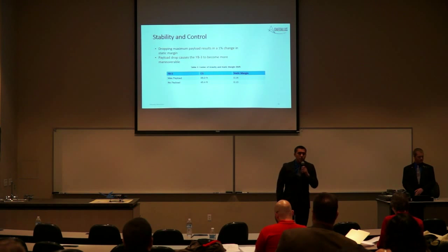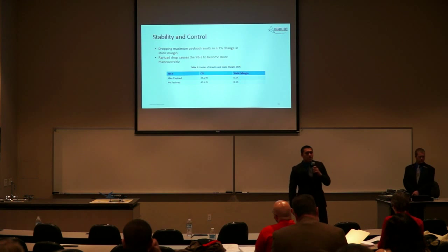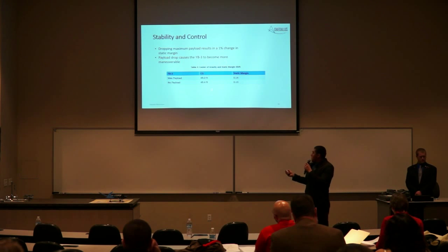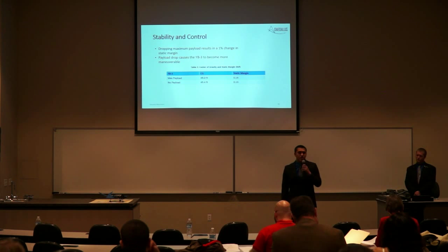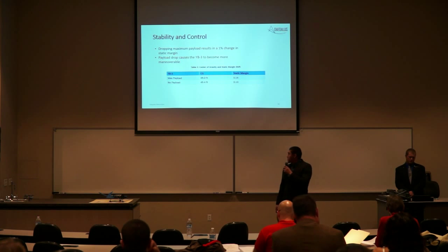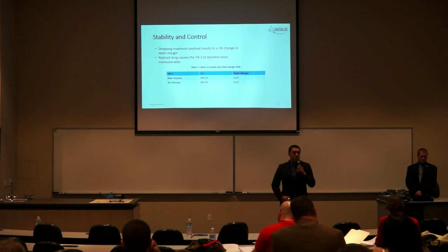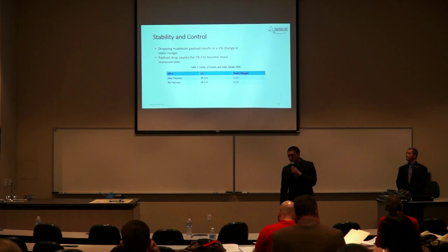By arranging the weights, the YB-3 managed to get a CG location from the nose of 49 feet with max payload, and with no payload, it's 49.4. This corresponds to a 14 and 13% static margin, respectively. This is only a 1% static margin change, which means that the YB-3 will become more maneuverable during flight. Keep in mind that Roscom says that anywhere between 10 to 15% static margin is acceptable for a large aircraft.